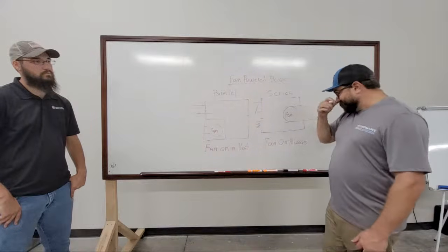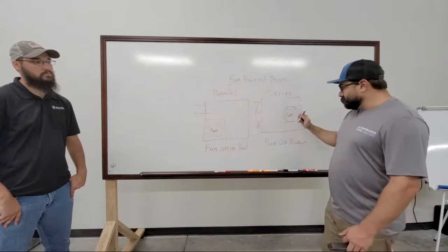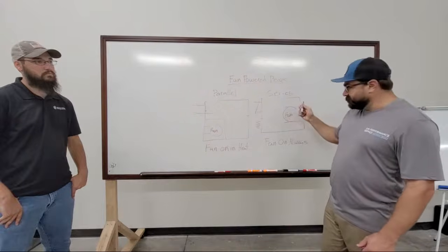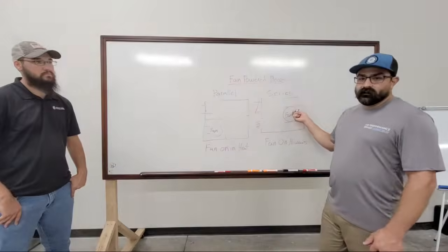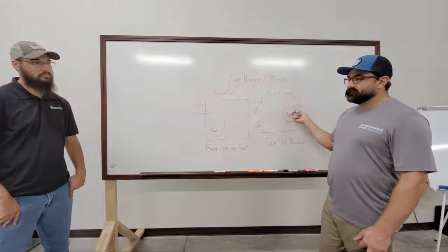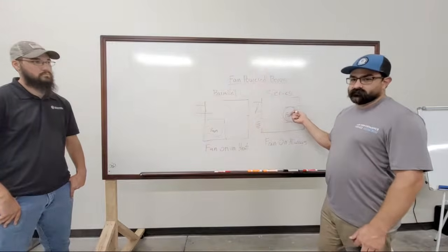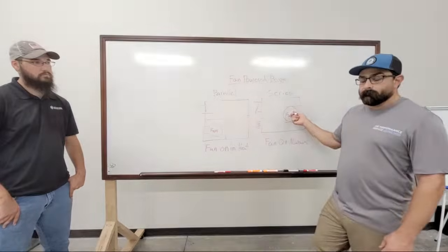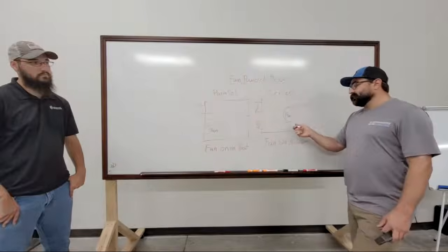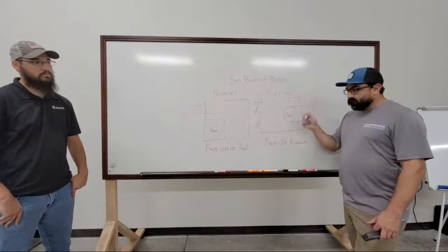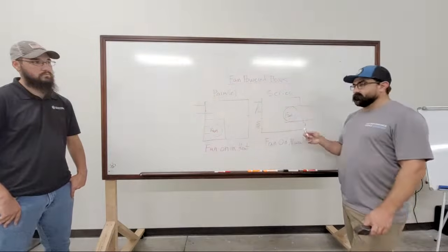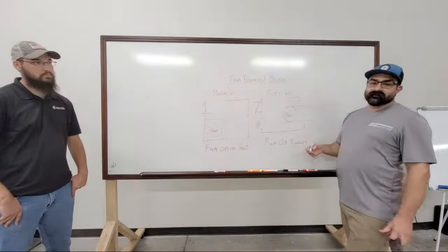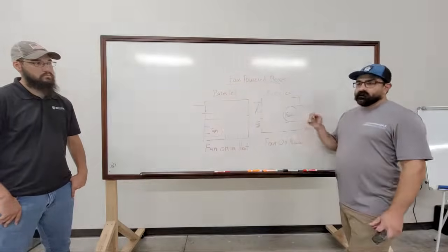One thing to note, I've written it here: anytime the building's occupied, this fan has got to be on. Anybody that tells you otherwise, don't believe them, don't trust them. They're wrong. Any actual mechanical engineer will tell you that fan needs to be on. Same thing with the guys that design the boxes. It's designed to run all the time.